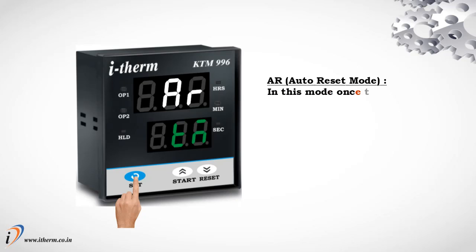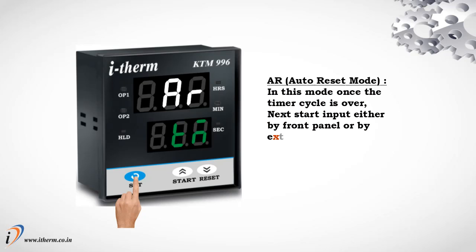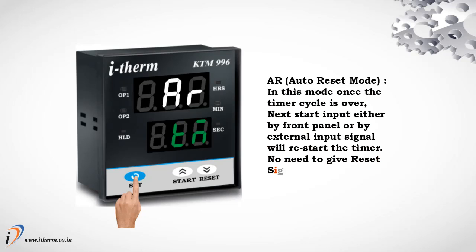Auto reset mode. In this mode, once the timer cycle is over, the next start input, either by front panel or by external input signal, will restart the timer. No need to give a reset signal.